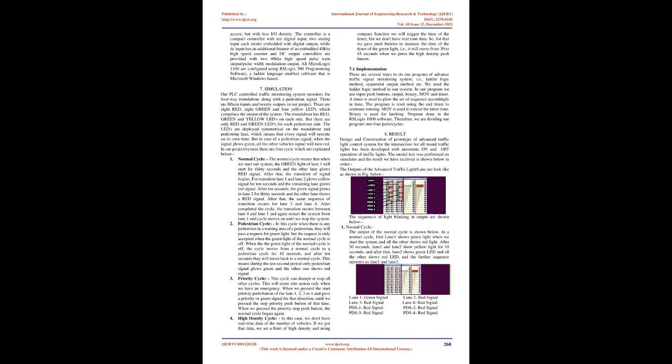These are the basic LED, 5 mm in size, working on 2 volt DC and 20 mA. It cannot be connected directly to the PLC as the output is 24 VDC. In the actual case, the traffic light is floating on 240 volt AC, but in the prototype case, it is 2 volt, so it can be connected directly.